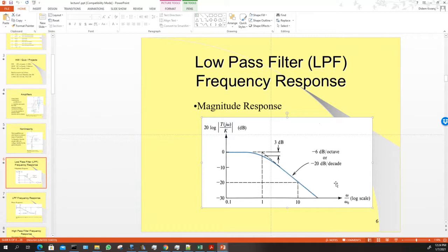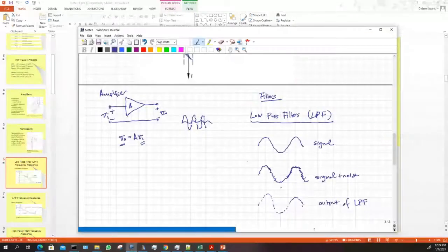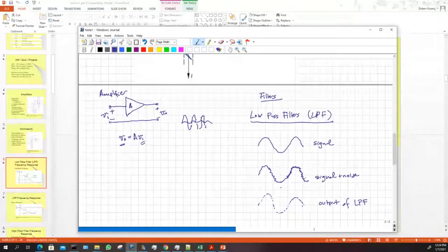It's not amplifying. I think we talked about decibels last week. This has decibels, and the x-axis will have a logarithmic scale. When the y-axis is in decibels and the x-axis is logarithmic, this is called the Bode plot. I'll just write down Bode plot. So you've heard it.